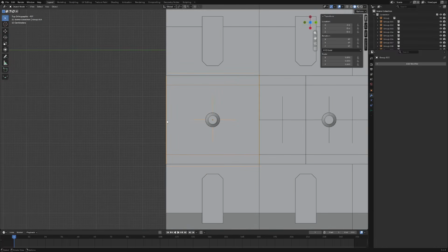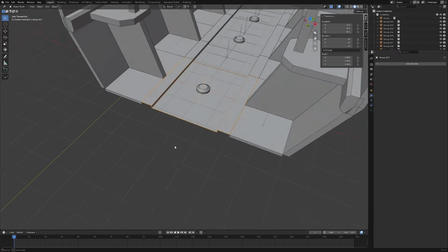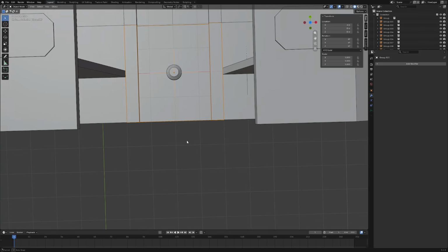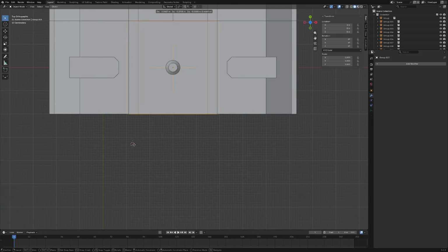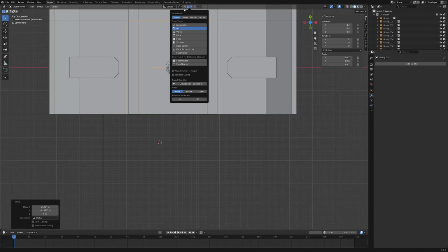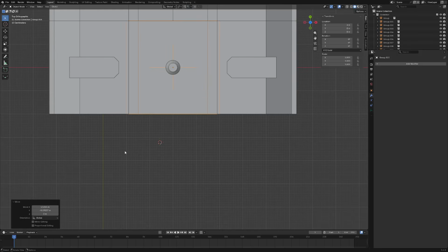So if I wanted to place something on the grid over here and I want to put the 3D cursor here, this is actually something you can do. You can use the 3D cursor. So you Shift right click. We have snapping on right now, right? Or we have snapping set to grid. So Shift right click and drag and hold Control. And you can set the 3D cursor this way.